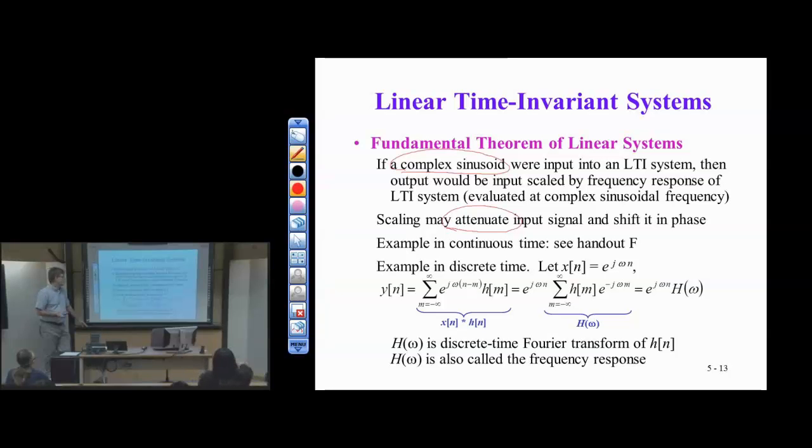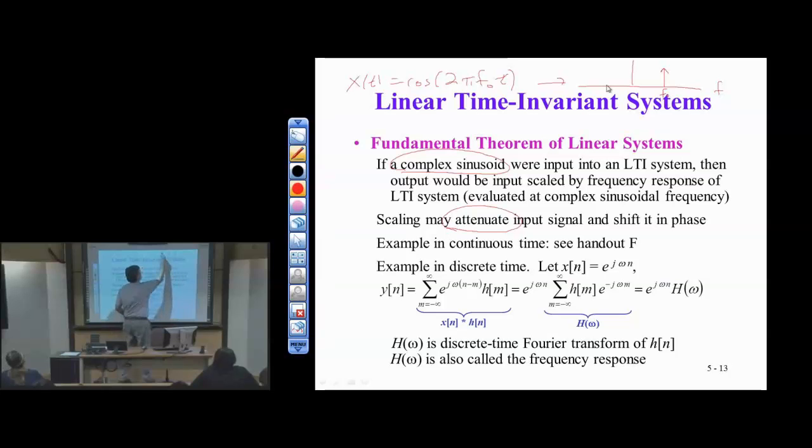So if the input signal is a two-sided complex sinusoid, for example x of t, then we know that the Fourier transform looks like what? Two impulses, one at f naught and one at negative f naught, and the area is a half, since I'm in hertz.